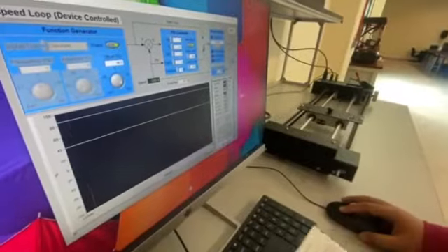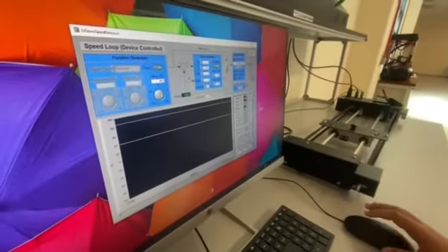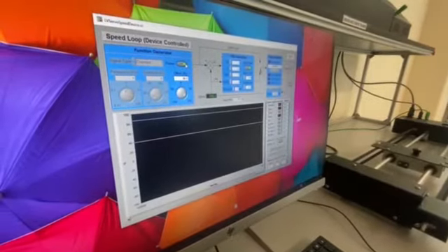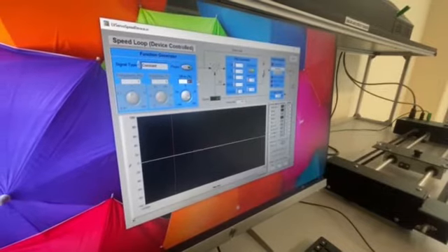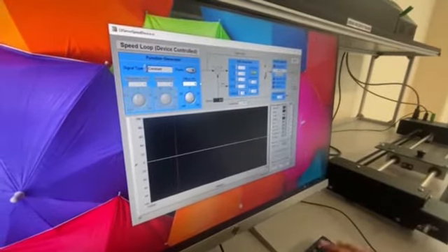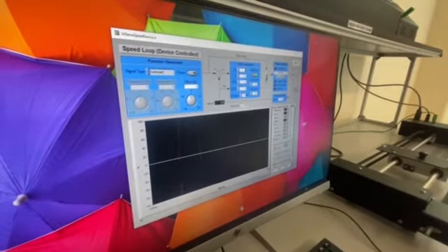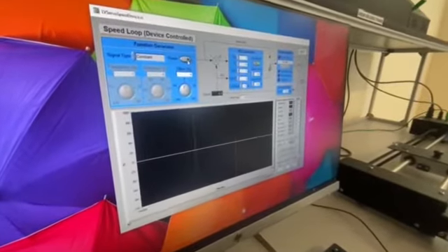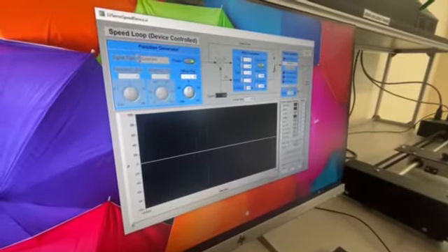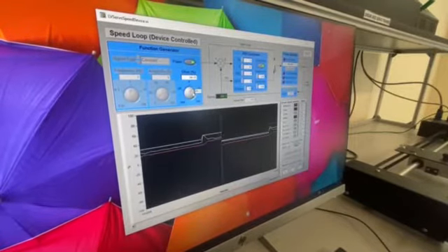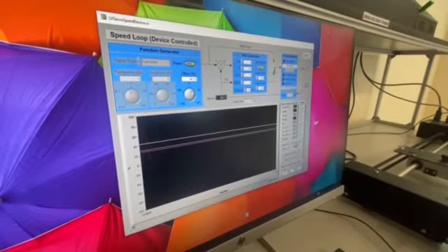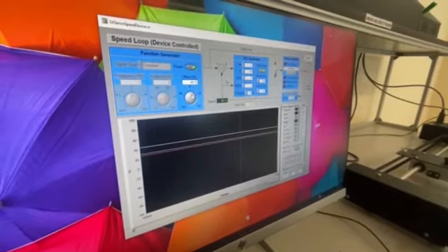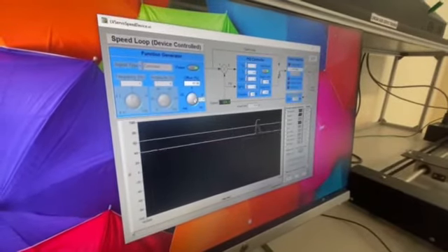Next, before we move to the second table, first we need to power off the software and change the offset value to 0. Then we change the value of KP to 2 and power on again, and change the offset value as well, but make sure the value is still at 40%.